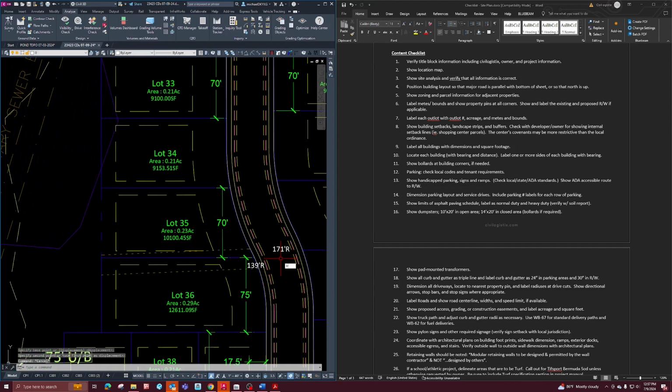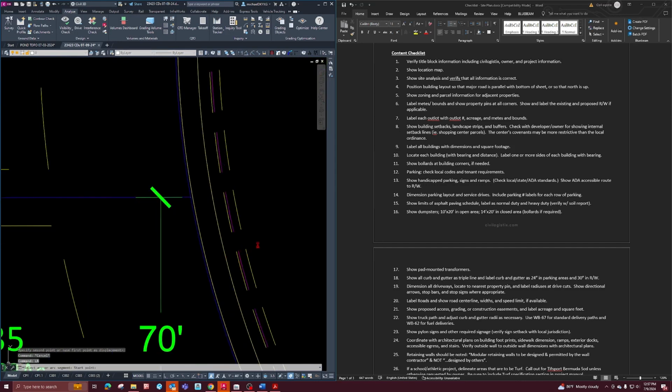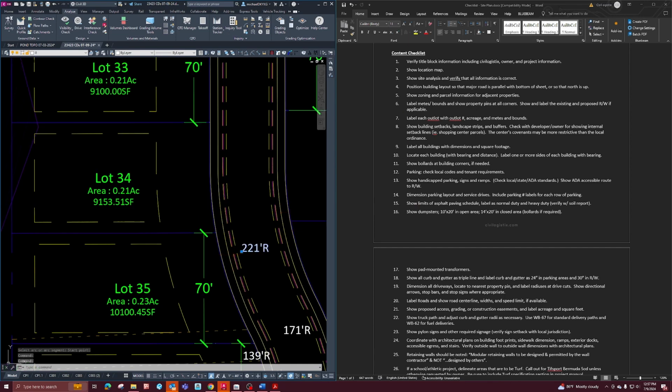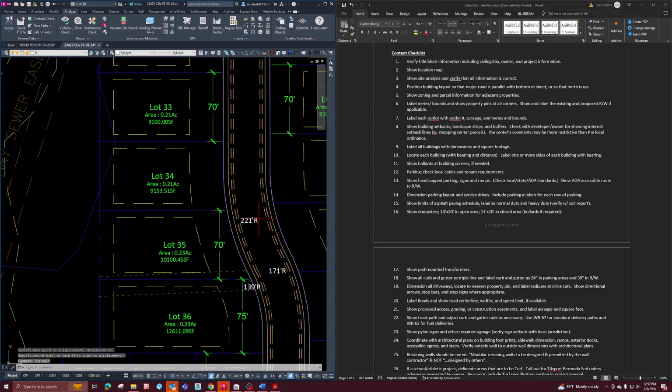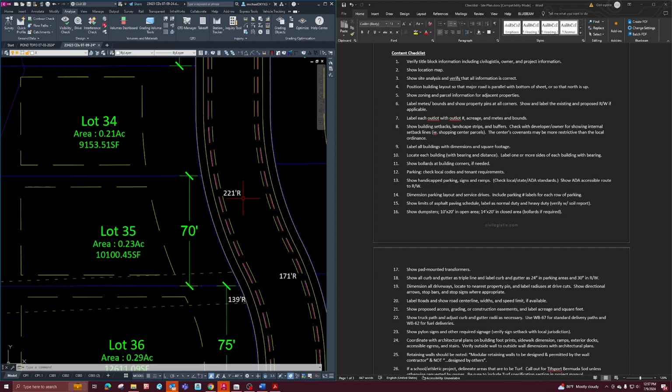And you would go along to each one of your radius along the road. I'm just setting the rotation to 0 on my properties tab on the other screen. This drawing is a 40 scale, so you would want to set the text height. You do 40 times 0.08, which is 3.2. So I'm just changing the text height over here. So that ensures that it's not too big and not too small.